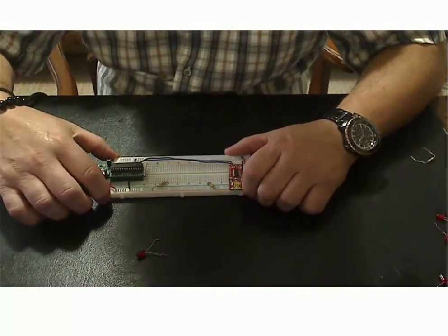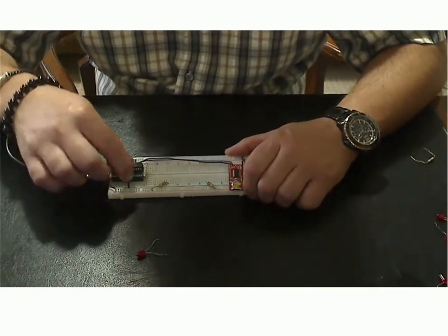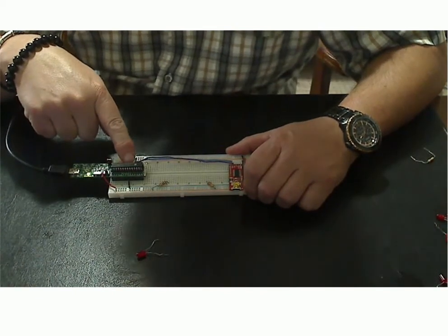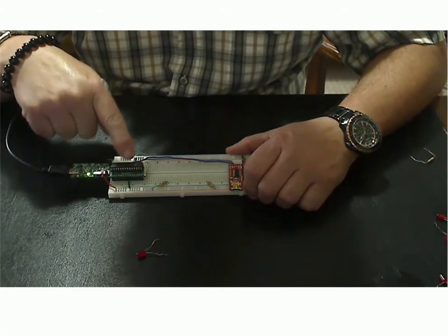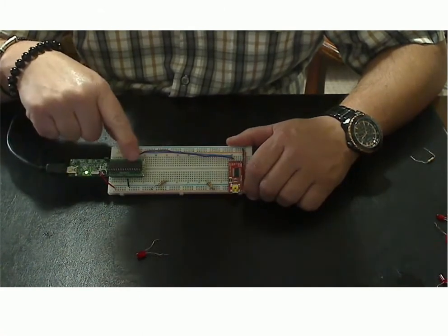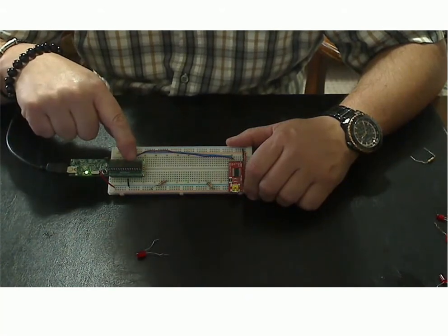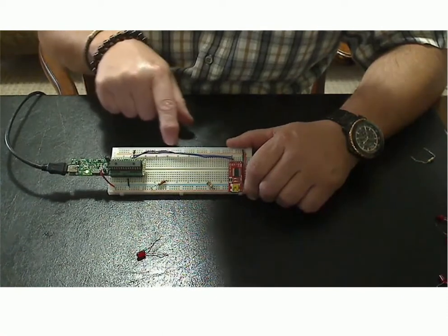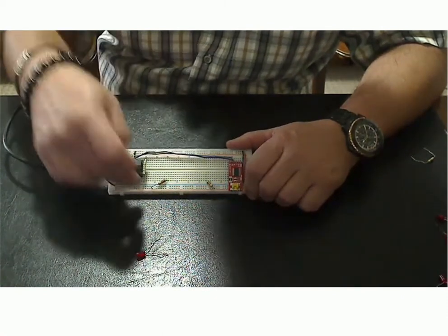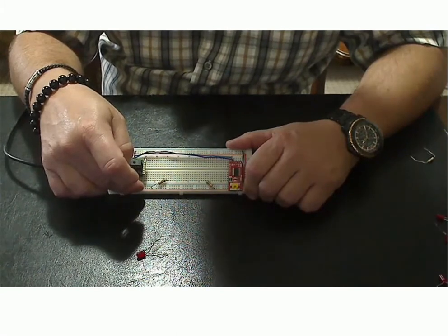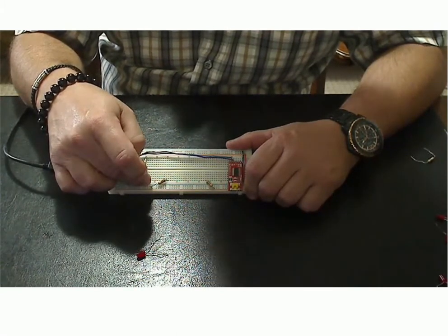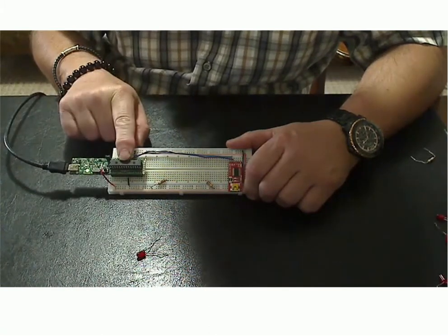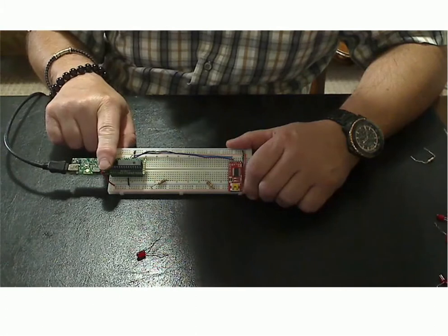Okay, welcome back. In today's lecture, we want to talk about digital input and output. We're going to concentrate on digital output. What that does is these different pins can be turned into the equivalent of the power and ground rails here. The power rail is set to 3.3 volts and ground to 0 volts. We can make an individual pin go high or go low, 3.3 volts or 0 volts.